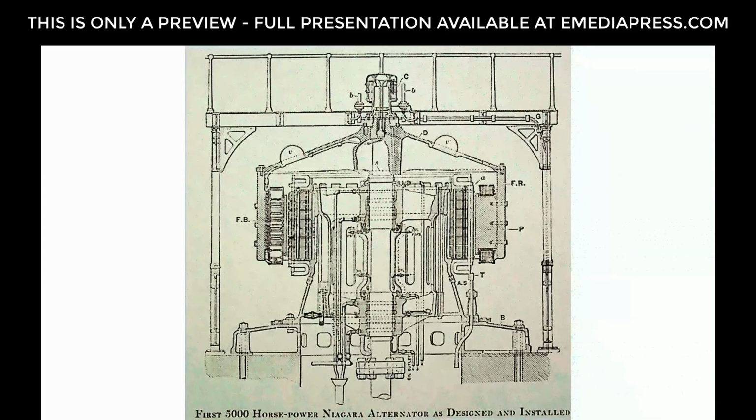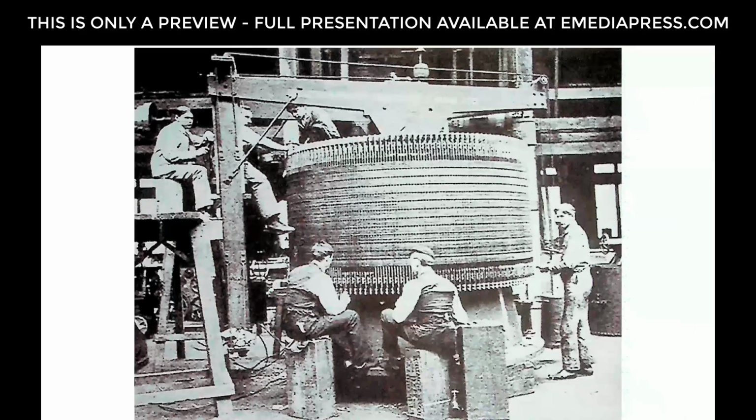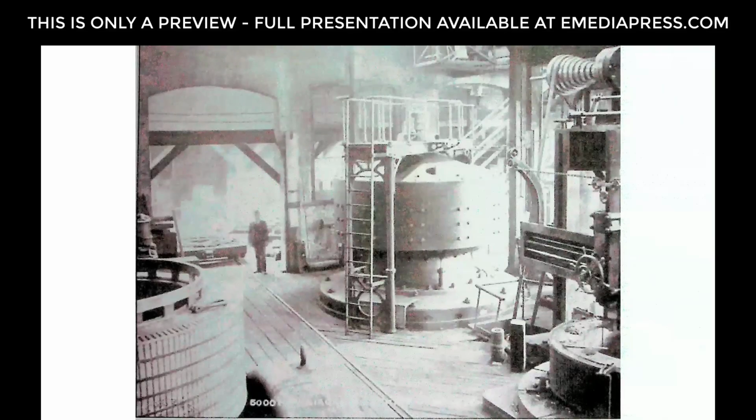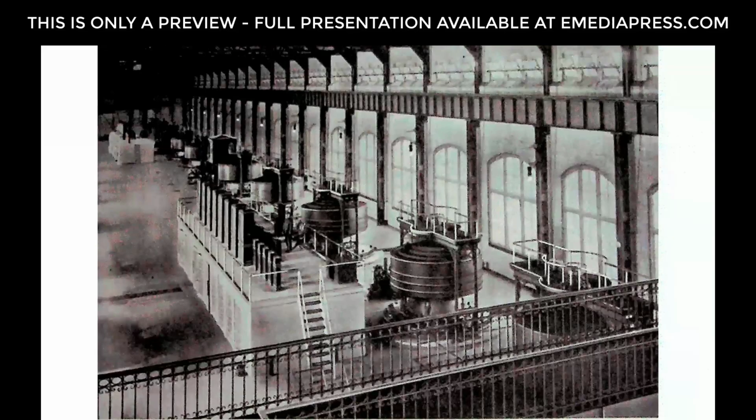So this is one of the alternators, a cross section. These were 5,000 kilowatt machines, 2,200 volts, and they operated at 25 cycles per second. This is the rotor, which provides the excitation field for generating the power in the stator windings. This is an enclosed unit. This is the final extension of the power plant. After Tesla and Westinghouse proved that it worked, then they extended it all the way out to 10 alternators. You can see the switchboard standing in the kind of mezzanine in the middle.